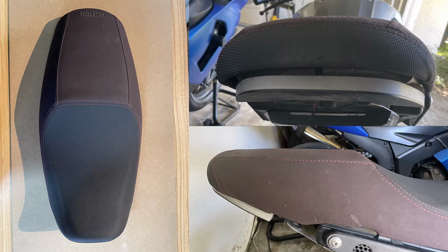At first glance, I didn't think it looked that bad. But when you look a little bit deeper, the seat is full of those complex compound curves that don't have a single dimension or a reference to grab onto. So you can take your calipers to it, but you can't get that many useful values. And when you can, it's difficult to reference those values or dimensions off of something else. So that's the challenge of creating these organic shapes in a parametric CAD software like SOLIDWORKS. And it's especially bad if you're trying to reverse engineer a part and need a more accurate model.